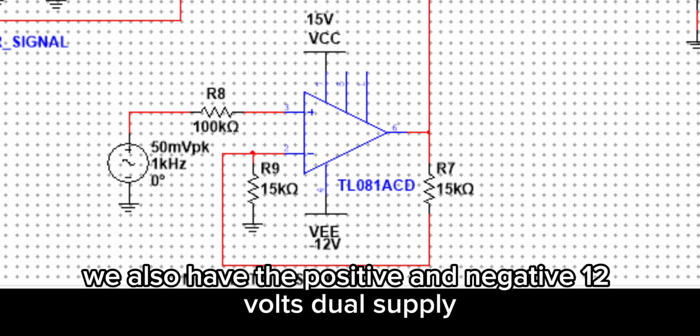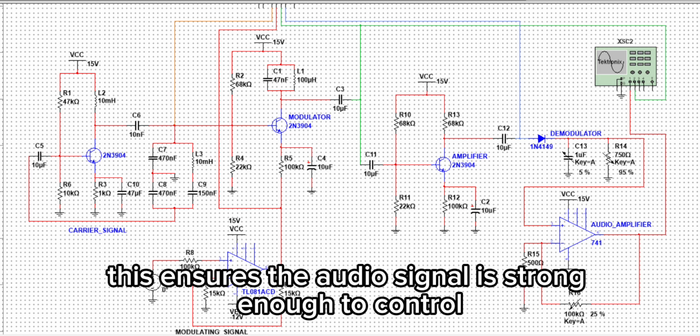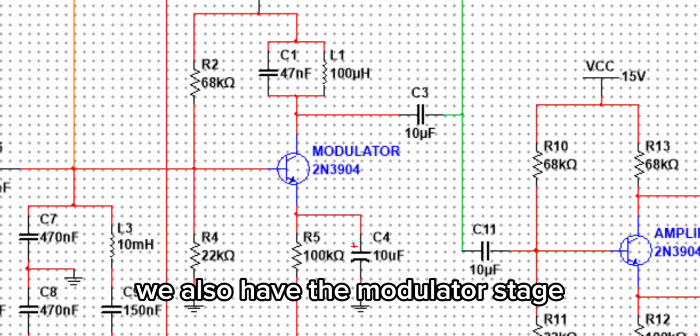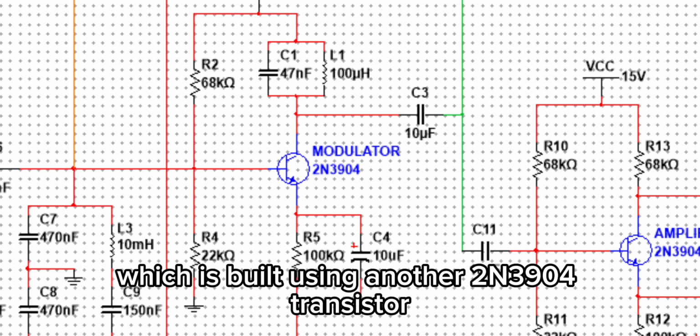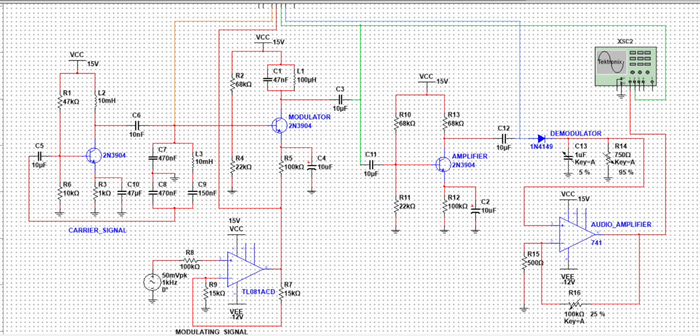We also have the positive and negative 12 volts dual supply. This ensures the audio signal is strong enough to control the modulator stage. We also have the modulator stage, which is built using another 2N3904 transistor operating in the active region.